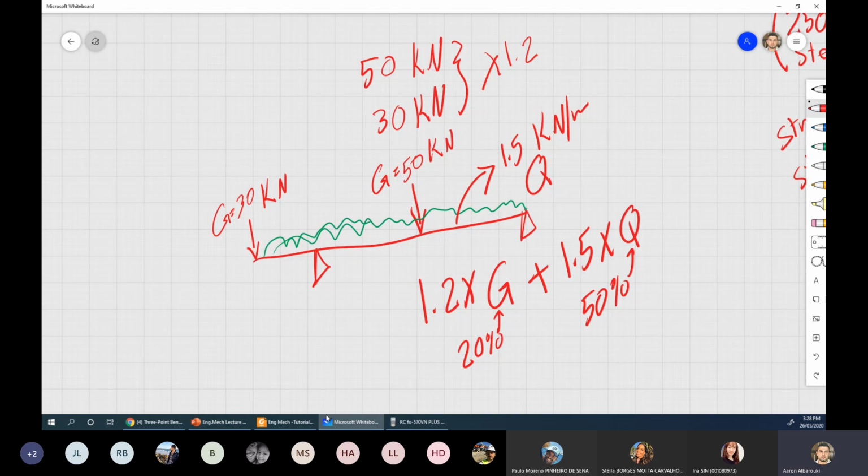So we have a more structured approach on this. And also, when I go to find the capacity or the strength of this beam, I multiply the strength of this beam by 0.9. That means I take just 90%. So this beam can carry 100 kilonewton meter, but my client can carry only 90 kilonewton meter.